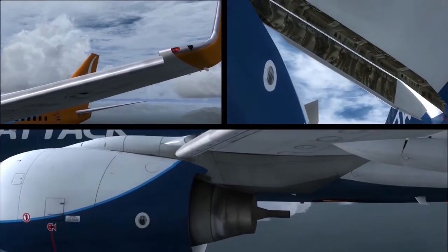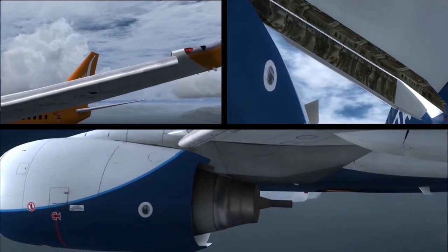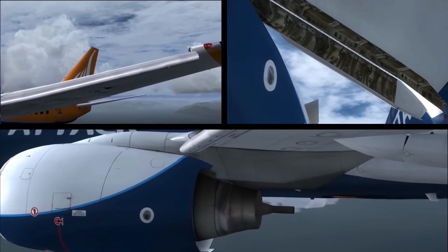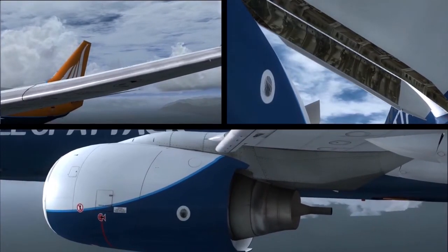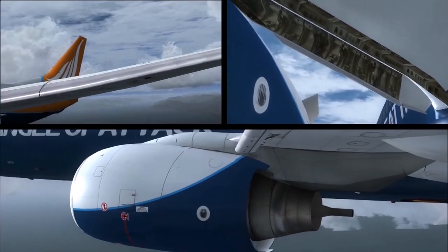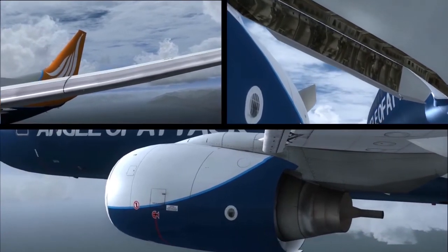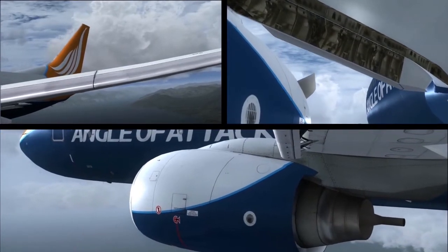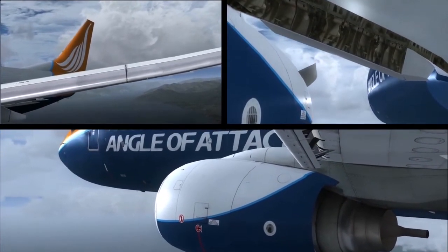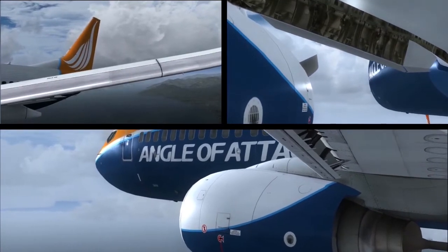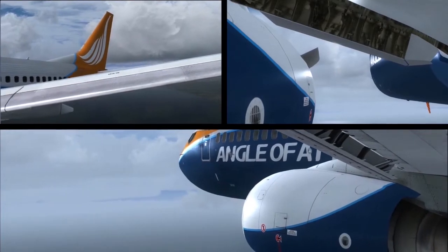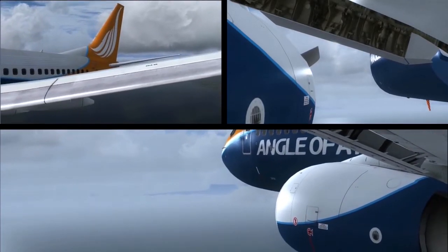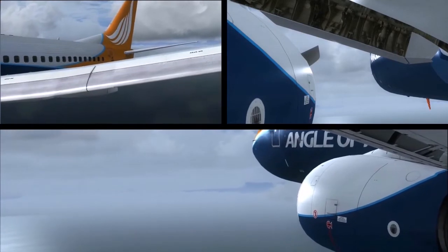Let's get back to the 737 now. Because the PTU is only used under such specific and rare circumstances, it is very rarely operated. The 737 PTU is also much smaller than that on the A320 because it's only needed to power the leading edge devices. Its smaller size means that it also generates less noise, so you cannot hear it from the passenger cabin. We talk a little more about the PTU in the secondary flight controls lesson, and we also cover the landing gear transfer unit and the landing gear transfer valve in the landing gear and brakes lesson, so we will not discuss those systems now.